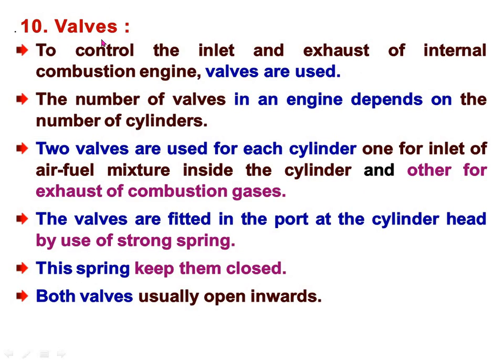Now, next is the valve. To control the inlet and exhaust of the internal combustion engine, valves are used. The number of valves in the engine depends on the number of cylinders. For each and every cylinder piston assembly, there may be two valves. One is the inlet valve and the second is the exhaust valve. One for the inlet of the air-fuel mixture inside the cylinder, and another for the exhaust of the combustion gases.